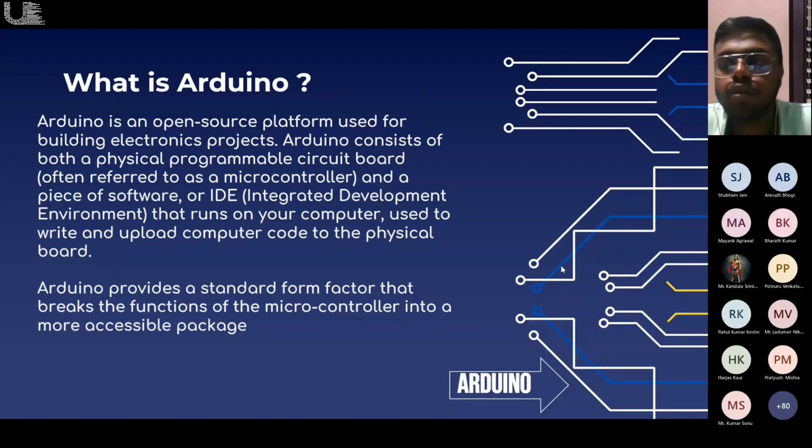If your project involves huge input streams like video recording or big computations, then the power of a microcontroller may fall short, because working with a video stream is a lot of data. At that point of time you will have to move to different methods, like a Raspberry Pi, which is virtually a small mini scale computer, and it can perform all the tasks that a computer can perform, but its size is very small and it is very handy.